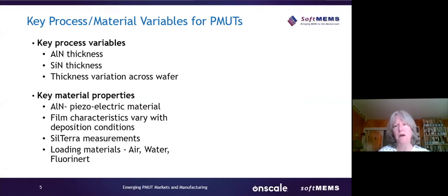We also need to note that the film characteristics vary with deposition conditions. So we've worked with SilTerra and they've taken measurements and shared them with us so that we can characterize the material properties and get really good simulation results.